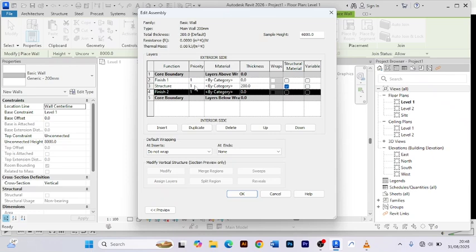Now here you can change a lot of things. First of all, we have materials. You can change the materials, you can change the thickness from these columns. First, we want to change the thickness. Most times for me, I create my wall at 200 millimeters because when you're using the common brick, that's mostly what we get. It contains a structure of around 180 millimeters. Then the finishes on both sides can be 10 millimeters and 10 millimeters.